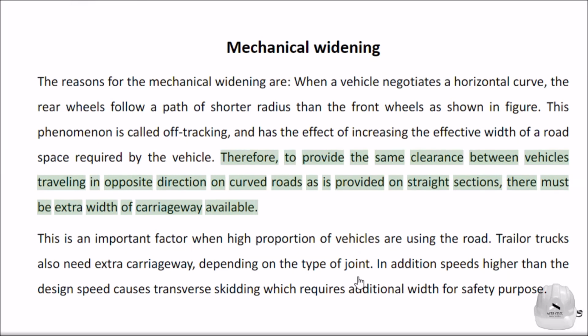Therefore, to provide the same clearance between vehicles traveling in opposite directions on curved roads as is provided on straight sections, there must be extra width of carriageway available.